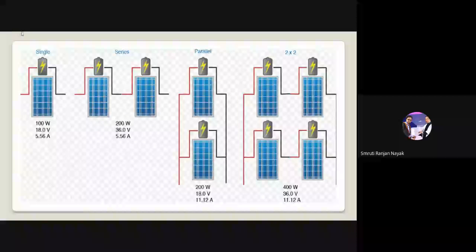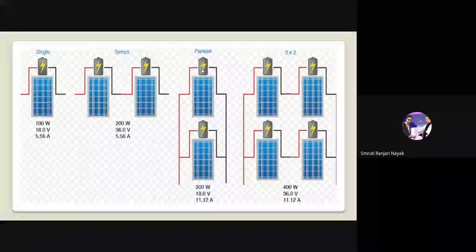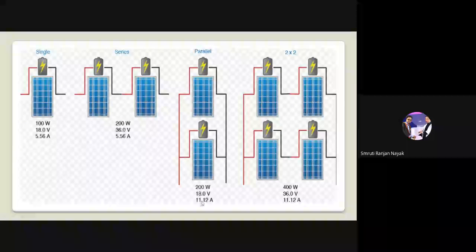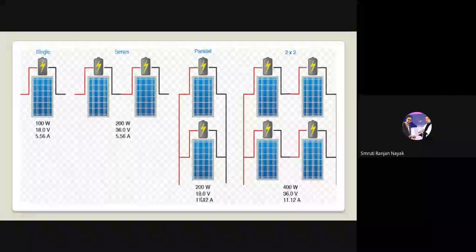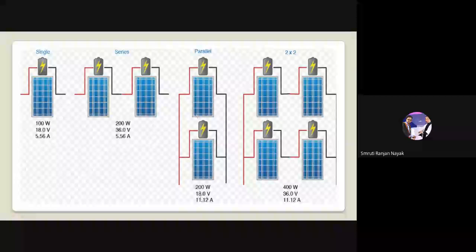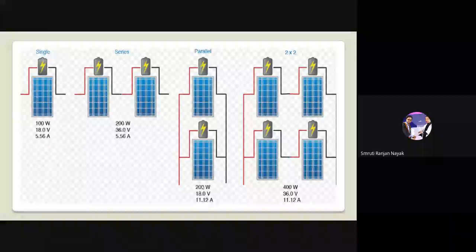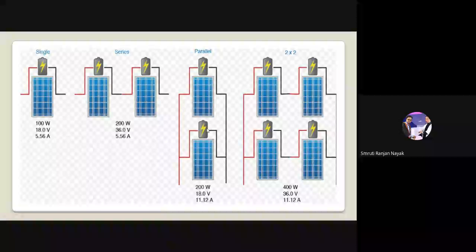But again, when these 100 watt panels are connected in parallel, then what happens? The current will be added and voltage is the same, and I mean to say that the power will also be added. So these connections are in parallel.